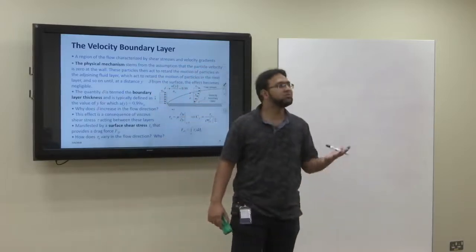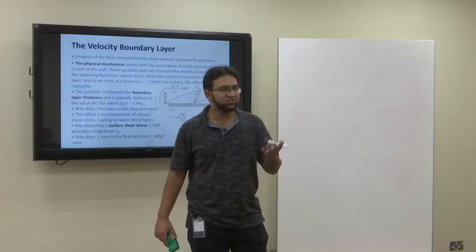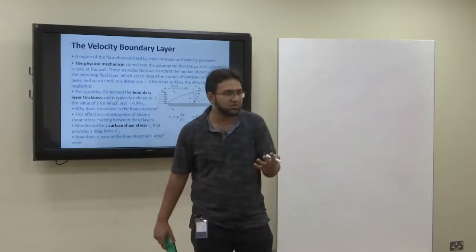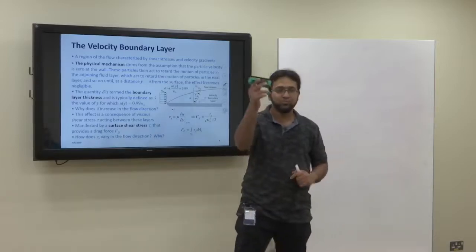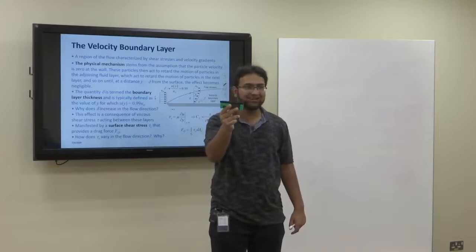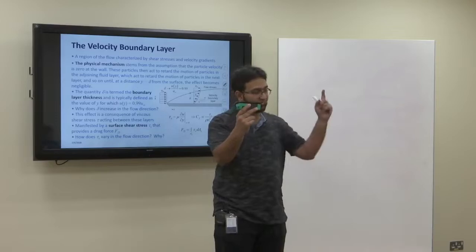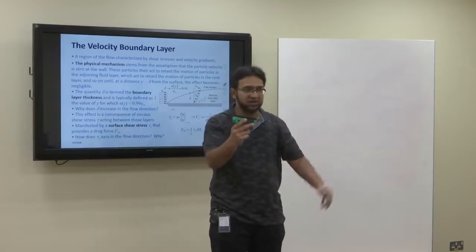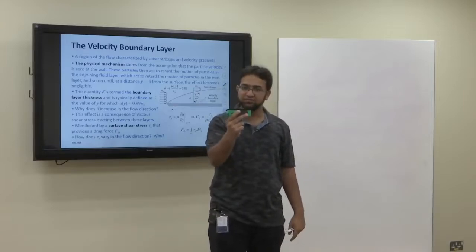Same velocity means no velocity gradient. Velocity gradient is change in velocity. So at any point, the velocity was 10 meters per second, so no velocity gradient. But now, when I put a plate which is stationary, this plate is going to give some disturbance, because the fluid was flowing smoothly with no velocity gradient, and now you have something in the path which is stationary.